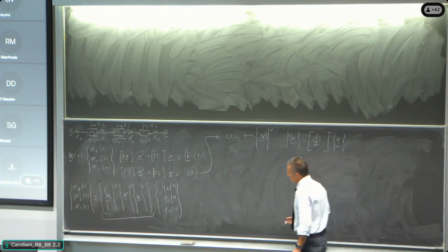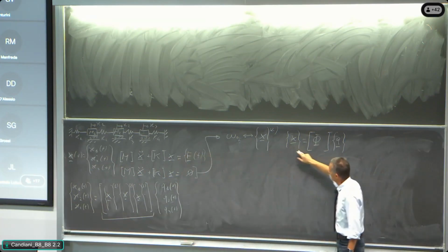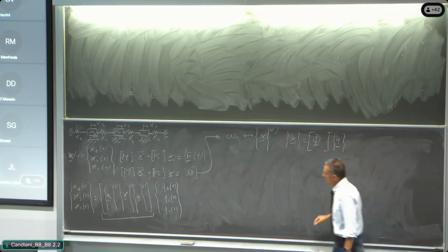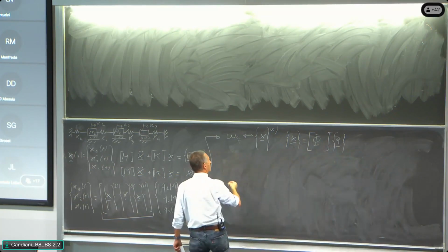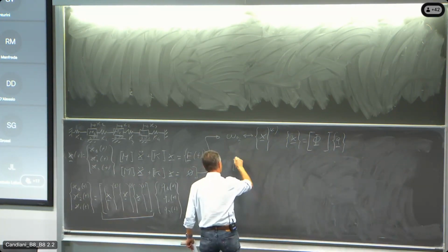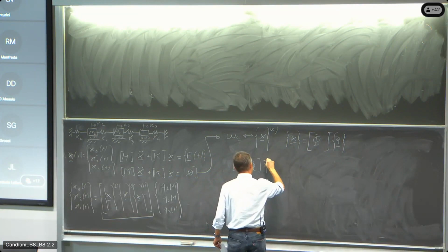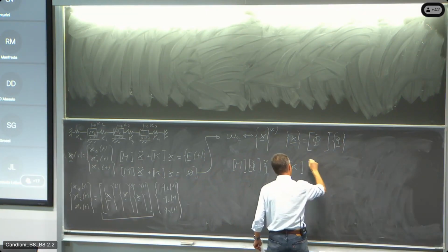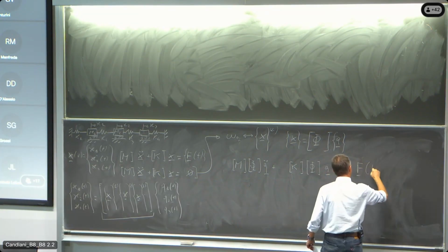So I make a substitution like that. The second order derivative of x will be the constant matrix multiplied by the second order derivative of q. And so I write M phi q double dot plus K phi q equal f.